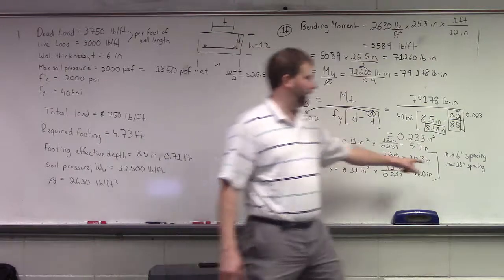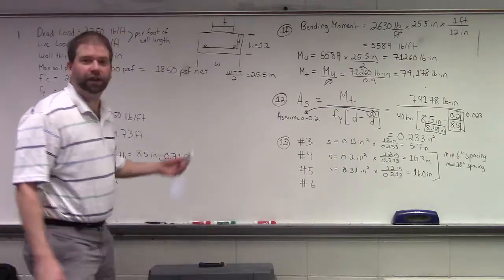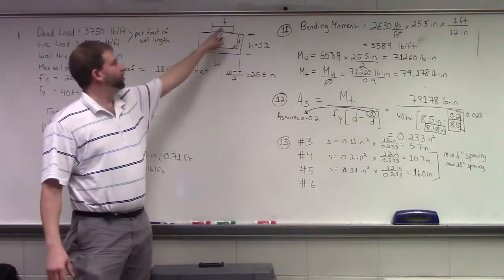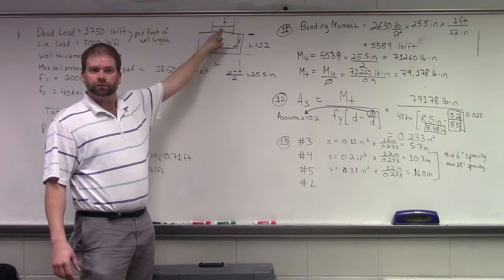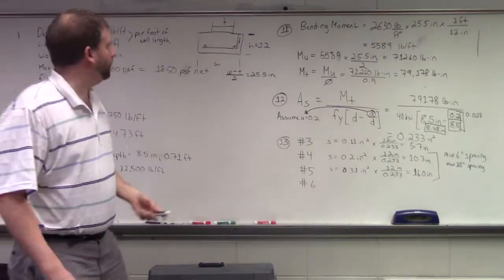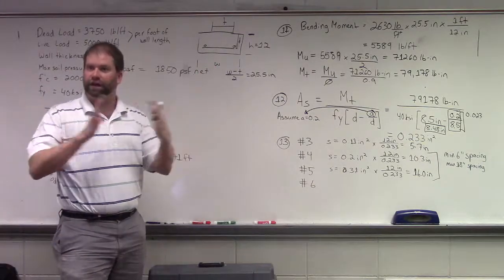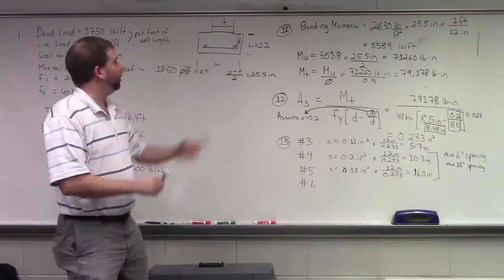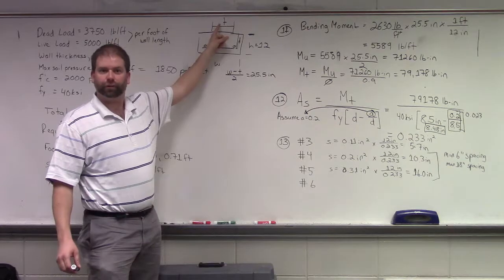It gives us the parameters. Typically speaking, what they're saying is you don't want to use less than the thickness of the wall, and you don't want to exceed 3 times the thickness of the wall. Another thing to keep in mind, from a general spacing standpoint, is what this wall is going to have in it for reinforcement.